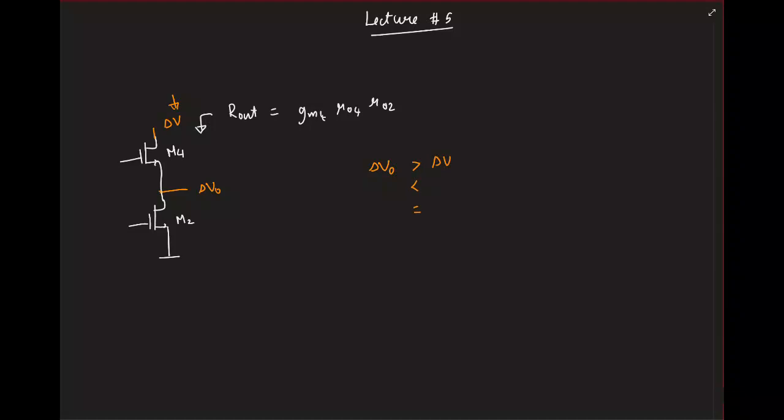Yeah, why? It is not a voltage buffer, right? It is a current buffer. A voltage buffer is when you apply the input at the gate and take it from the source. But here, the voltage is applied at the drain, right? I'm guessing the current should be constant, the VGS should be. Okay, why is the current constant?